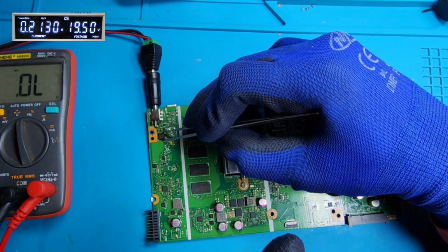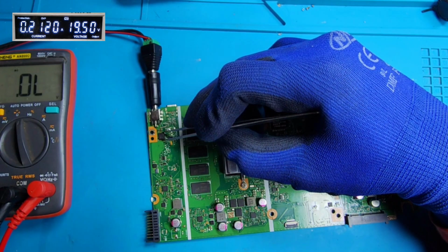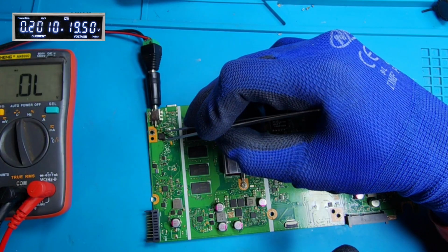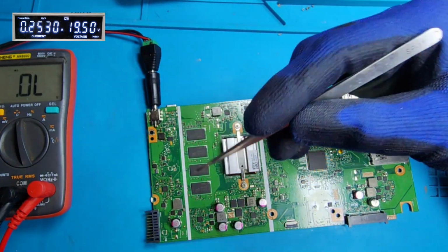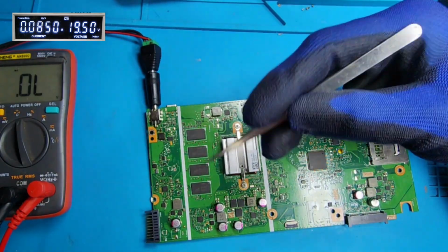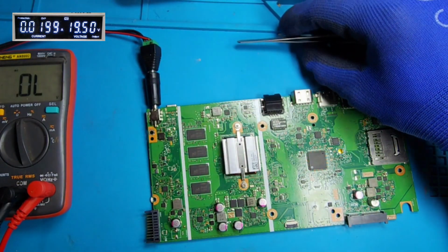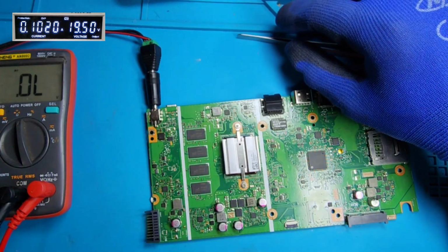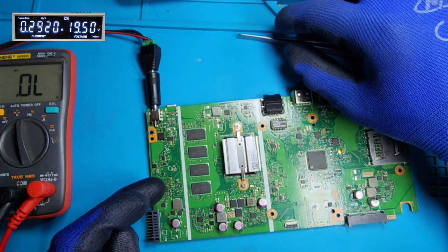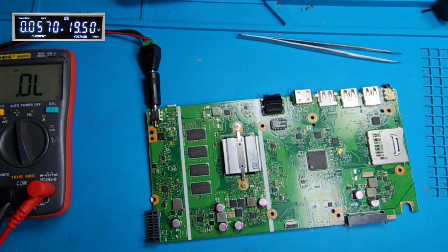Okay, now it is stable, right? So now it is stable, and I think we got the display. If I take it, yeah, it is shutting down. Then again it is restarting again and again. Okay, so the main power rail is actually turning on and off by the charger IC here. So that is the problem. So we need to find why it is behaving like that.